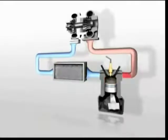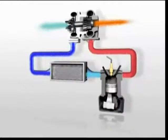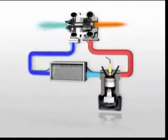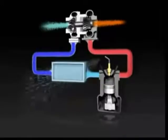In theory, a turbo is simply a hot air pump that forces more air into the engine. With more air, the engine can generate power more efficiently, improving performance, reducing fuel consumption and cutting emissions. As temperature increases, density decreases, which reduces power. So it's usually passed through a charge air cooler or intercooler, which uses air or water to cool the hot,